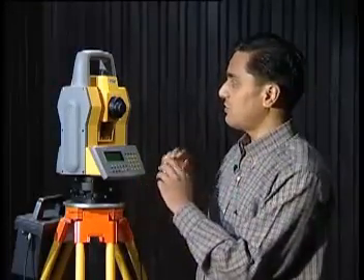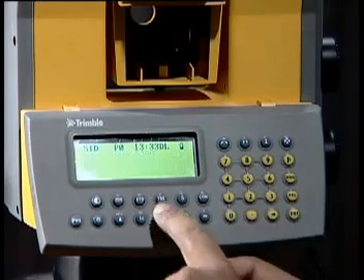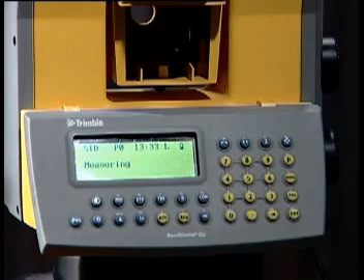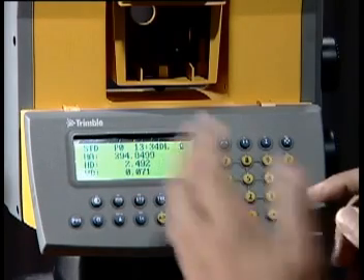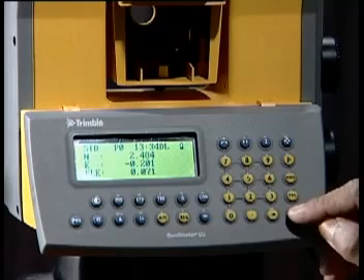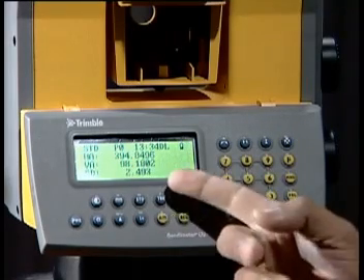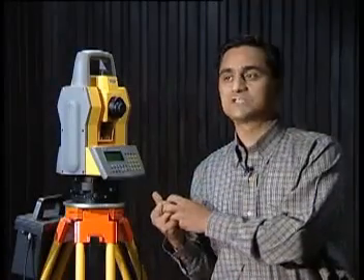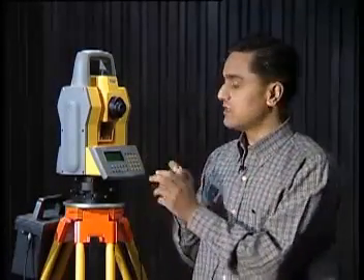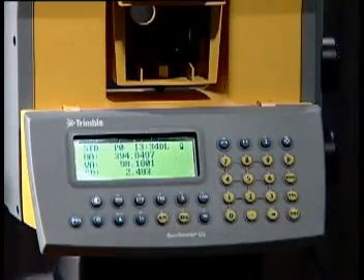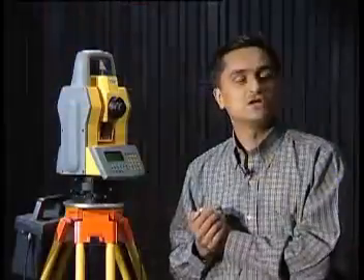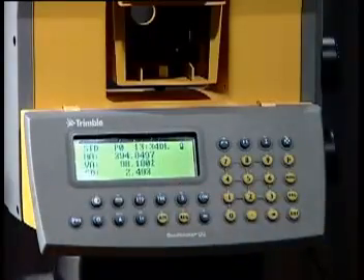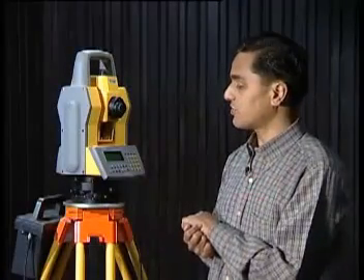So what we can do now, I am measuring now. Again, to measure I am using this A/M, and now it starts scanning and doing the measuring, and now it is giving me again the coordinates of that particular point. If you see the sloping distance is 2.493 meters. Regarding the units, I have fixed the units here. Right now the angles are being measured, it's up to 400, you can see, in gons. It's not in degrees, we'll have to change it. Also the distance is being measured in meter. So we can change these units inside this instrument, and all the computations can be done accordingly.